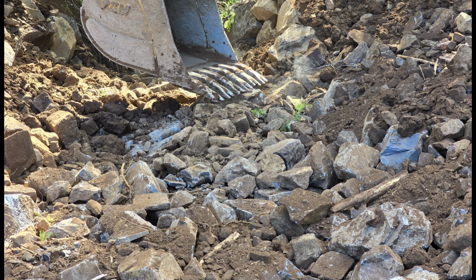The rock used to build a vertical grade control structure and to armor a slope should be from 6 to 12 inches in diameter. The rock should be angular or fractured so it fits tightly together like the pieces in a puzzle. It's best if the rock is not washed clean and contains fines so it can be compacted.